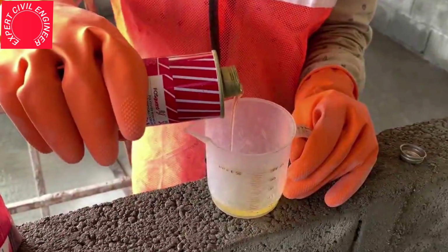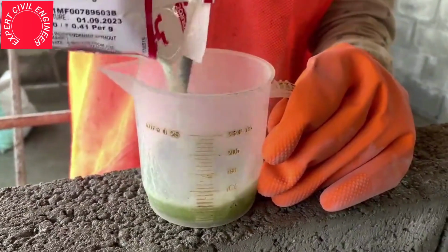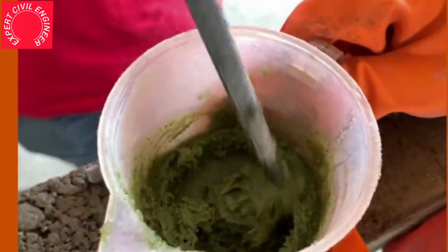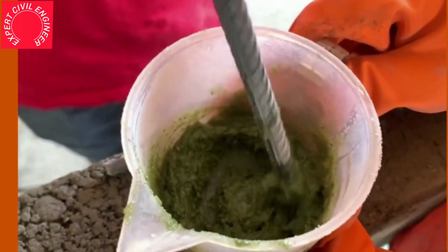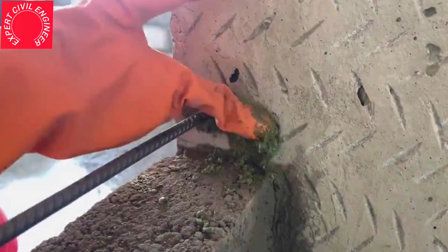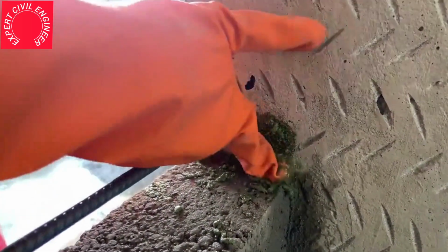Following the manufacturer's recommendations, it is of utmost importance to thoroughly mix the materials, commonly referred to as Part A and Part B. The mixed material must be utilized before the completion of its setting time to ensure optimal performance and adherence to specified curing requirements. The anchoring chemical should be initially filled entirely inside the drilled hole and leveled. Subsequently, the same chemical should be applied above the rebar.